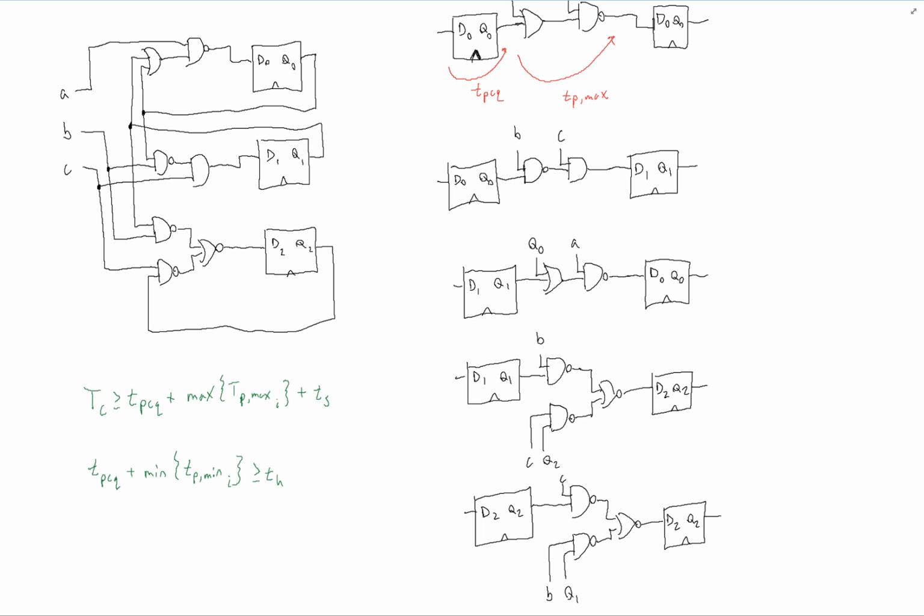Overall, we have seen how the various properties of a sequential circuit influence the clock frequency that we can use for the system. The setup and hold times of a flip-flop provide some rigid rules that must be obeyed around the clock edge in order for the flip-flop to function properly. Additionally, the intermediate combinational logic provides some constraints as well, since it also presents a propagation delay. Taking all of these factors into account, we can find the maximum clock frequency for a given sequential circuit topology.